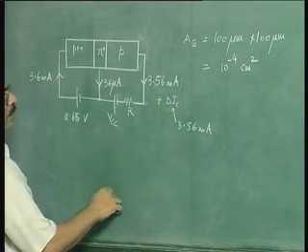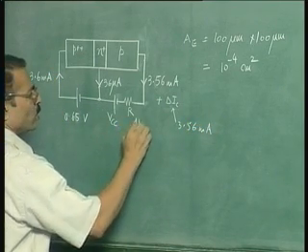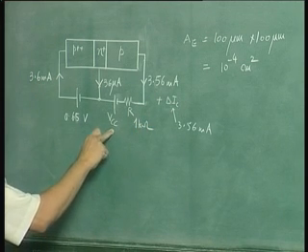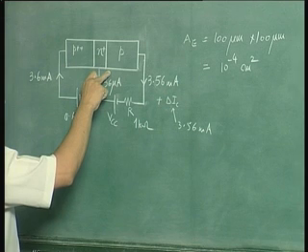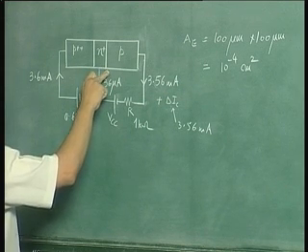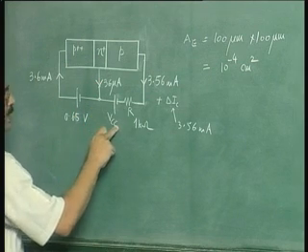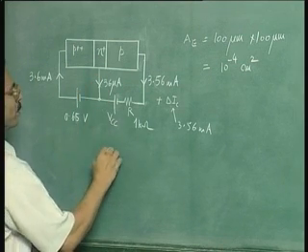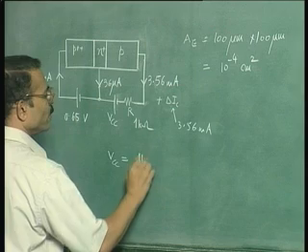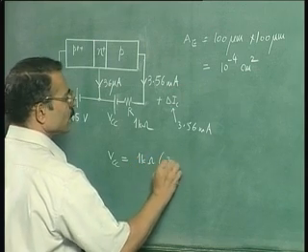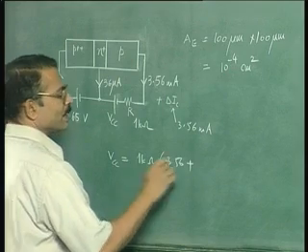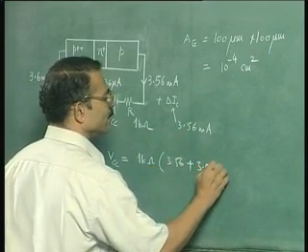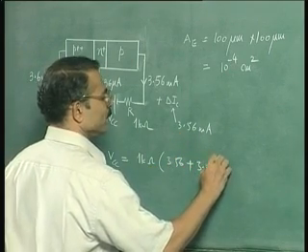So if delta IC is exactly equal to 3.56 milliamperes, and if R is 1 kilo ohm, the value of VCC that you will need so that the collector base junction always remains reverse biased, or at most becomes zero biased, would be VCC equal to 1 kilo ohm into 3.56, that is the DC quiescent current, plus the incremental current, another 3.56 milliamperes.